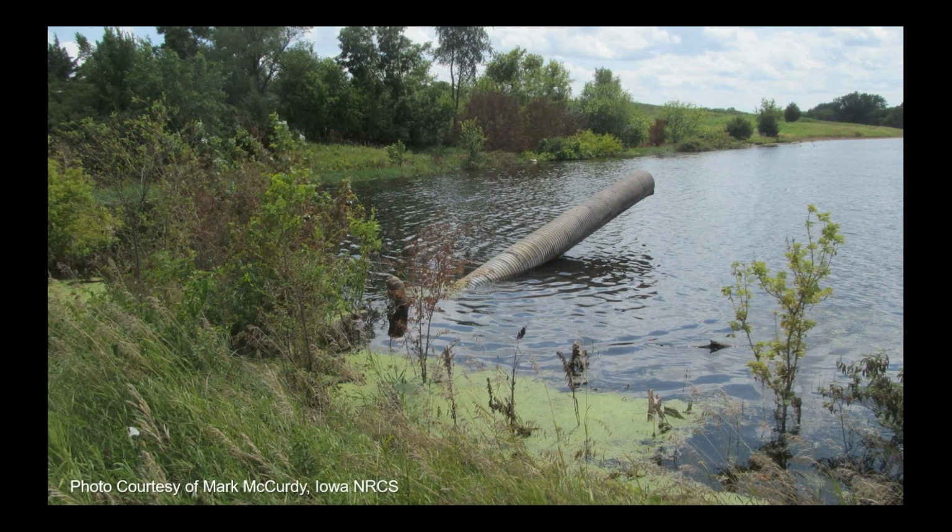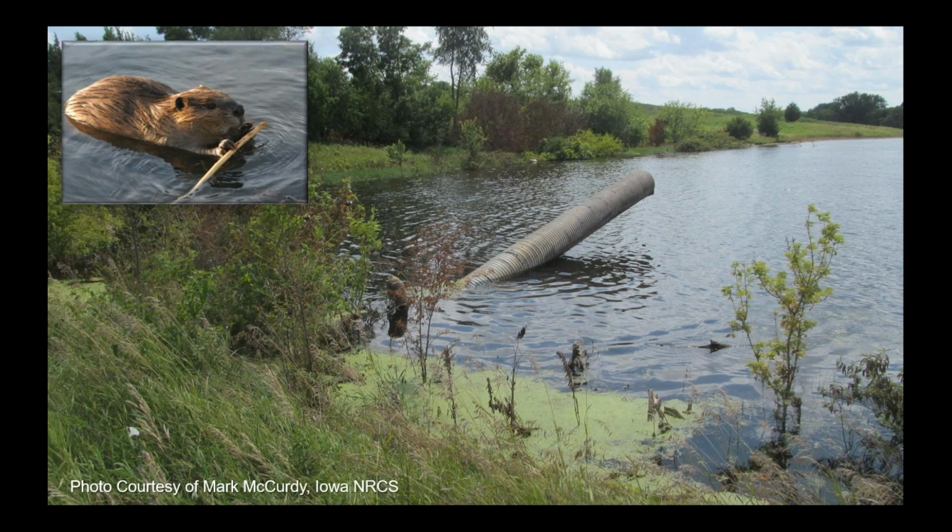And this is another unusual case. And I remember when Mark sent me this picture, he said, Paul, do you know what's going on? I went out to my dam one day, and all of a sudden the intake pipe that went to the riser structure was in this configuration. And my theory is, again, this is probably related to beaver activity, where the beavers got busy and they clogged the entrance to the riser structure, and that dewatered the pipe that was submerged. And because it was a corrugated metal pipe, it floated. It didn't have enough weight to keep it down, and it just floated up above the reservoir. So just another thing to look for.